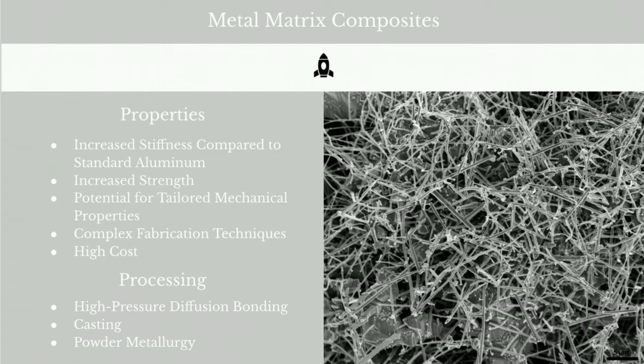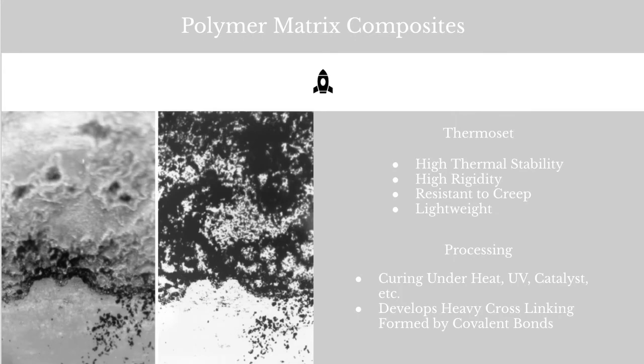Graphite aluminum was used to form the high-gain boom antenna on the Hubble Space Telescope for its desirable stiffness and electrical conductivity, and boron aluminum was used to construct the frame and truss members of multiple parts of the Space Shuttle orbiter in the form of tubular struts and provided a weight reduction of 45% as opposed to if typical aluminum alloys were used.